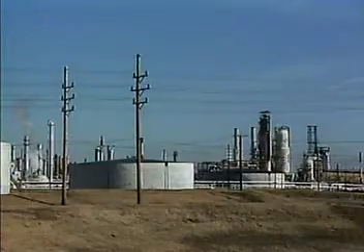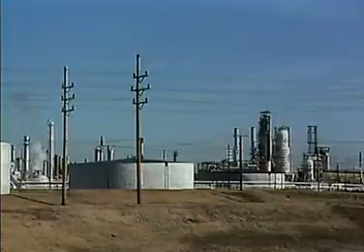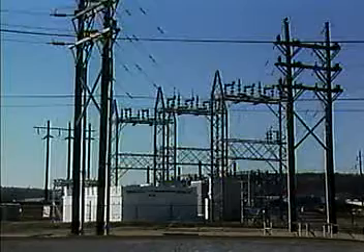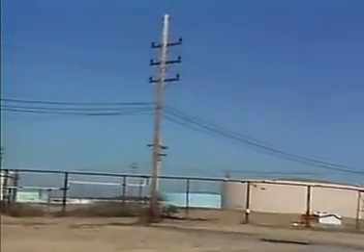Your plant probably has rules and guidelines to help people do their jobs safely. Follow these rules to the letter when you work around electrical equipment. A knowledge of basic electrical safety rules, combined with a good understanding of your company's policies, can reduce the hazards related to electrical equipment. Your plant probably uses a series of overhead lines to carry electric power. At some point, you may come across a downed power line. You should always assume that downed power lines are live, and a live line can electrocute you or cause a fire. If you see a downed line, report it immediately.